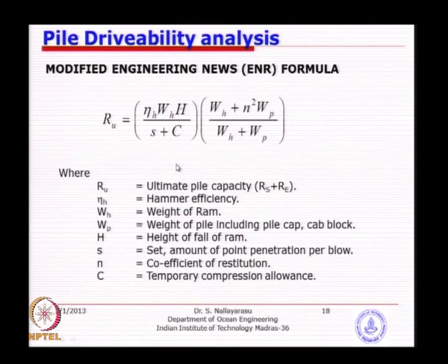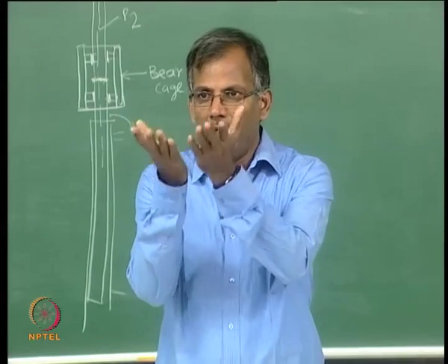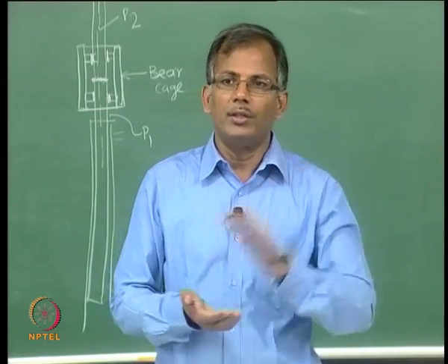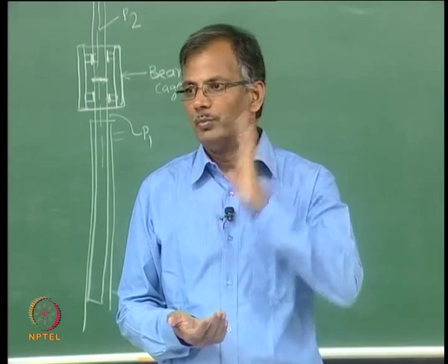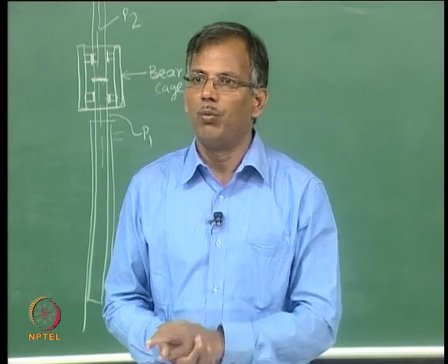How do we determine whether the pile can be driven or not using this formula? It is very simple. When you design a residential building with a pile foundation or shallow foundation, we limit the displacement criteria. For example, the maximum vertical displacement is 1 inch.